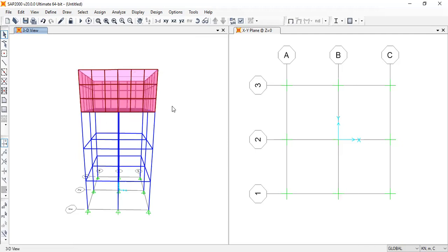I have told this in earlier tutorials as well. If you go from left to right, only the full elements will get selected. If you go from right to left, whatever the things in the box will get selected, right?